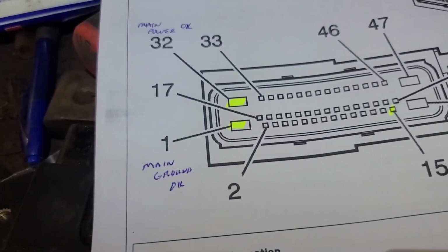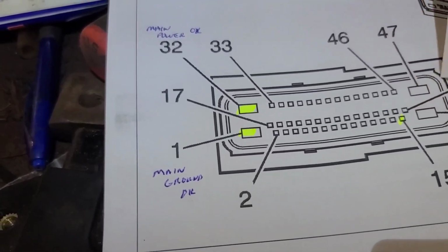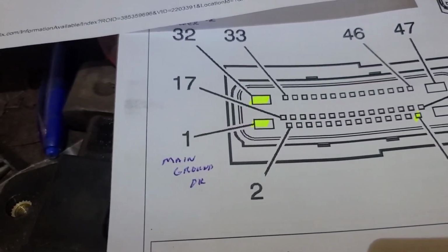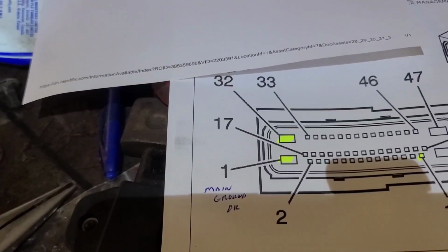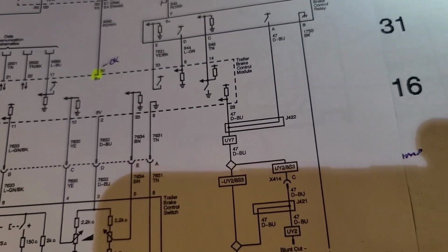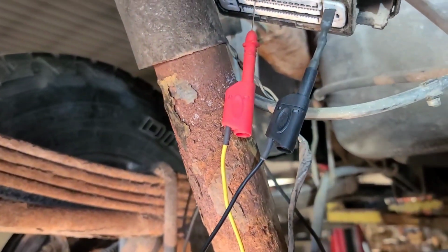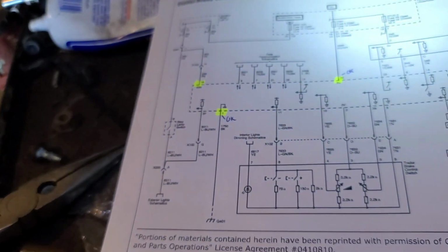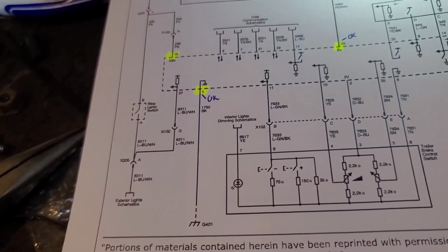And 29 is one of these pins in here. 31, 17, so I'll check that. Well, it's actually pin 28. It's a dark blue wire. It's the fourth in on the second row on the same line as pin 1, the ground, so it lights a 500 milliamp bulb. So that feedback circuit is okay.